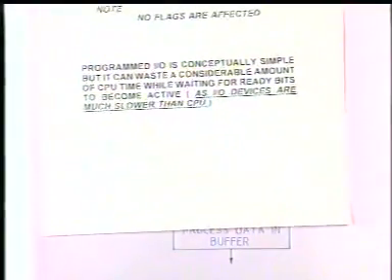With the use of input and output instructions, you can transfer the data between the peripheral and the CPU. But when you do this, the CPU is not doing any useful or meaningful job, because it is waiting for the ready bit to be on. The CPU, which is mainly for number crunching or computation, is not doing that. It is totally blocked in the input-output communication.